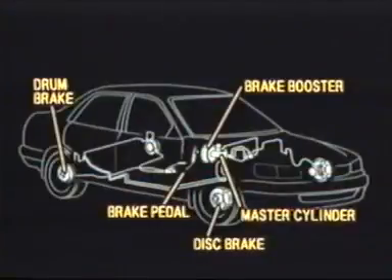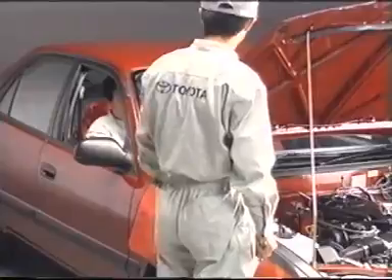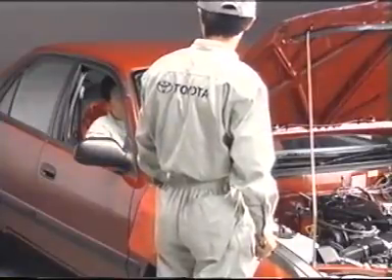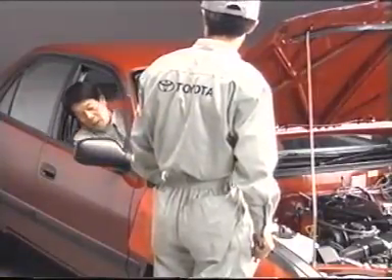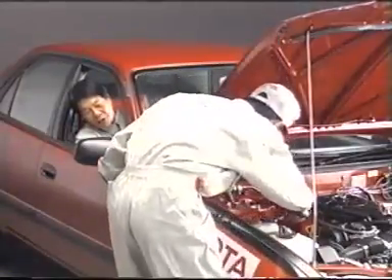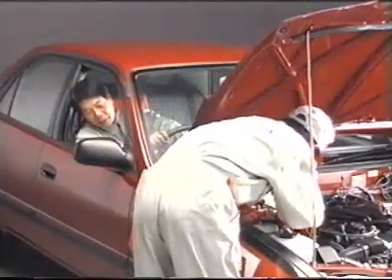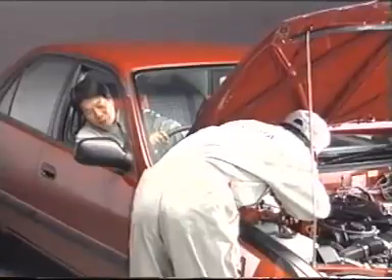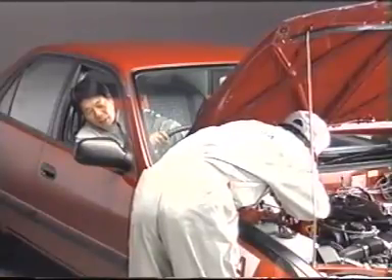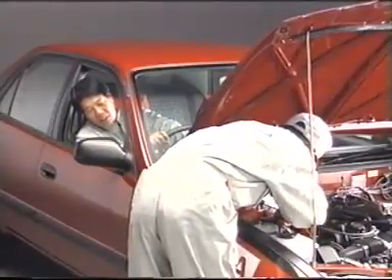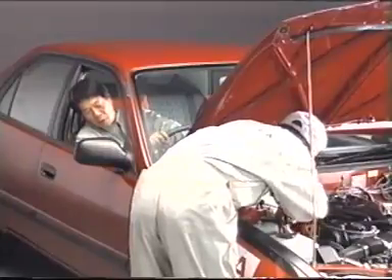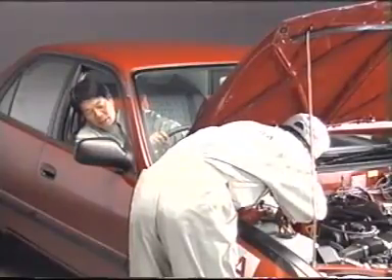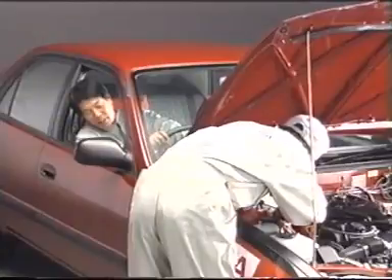If air is contained in the hydraulic circuits, the pedal feel becomes spongy. All air must be bled from the system whenever there is a possibility of air contained in the hydraulic circuit, or each time after disassembling the hydraulic circuit of the brake system. 2 people should conduct the operation. Use mutually understandable signals and confirm each step of the operation with each other as it progresses.